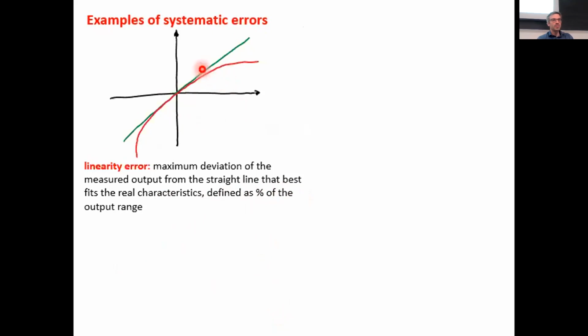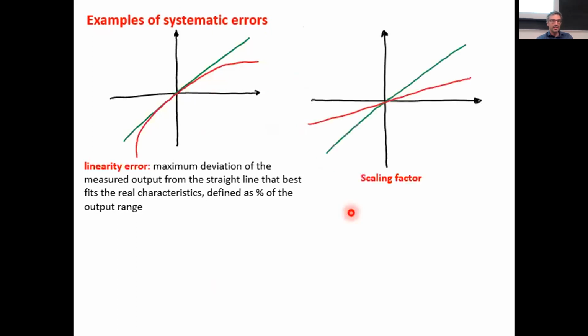So you will try to design your system. So select your load cell. If my load cell that we selected for a 5,000 Newton range is linear only up to 3,000, and my maximum force I'm expecting is 2,000, I'm fine. If I get 4,000 force, I will know that my reading will be wrong, out of the linearity range.